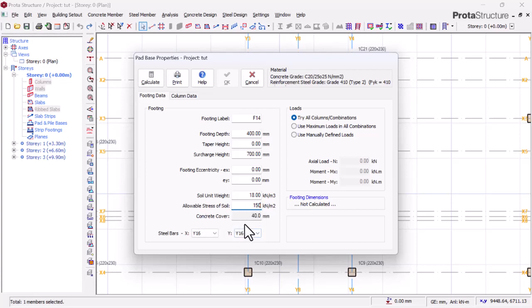Our concrete cover, we're going to allow to be 50 or 40 as the case may be. Let's allow it to be 40 on site. You can consider using 50, but for the purpose of this design, we'll use 40. What will be the depth of our foundation? Let's use 150, so we'll have a sufficient depth for our foundation. We're going to include the footing depth, look at our soil strength by checking the soil, and check the bars we are going to use.